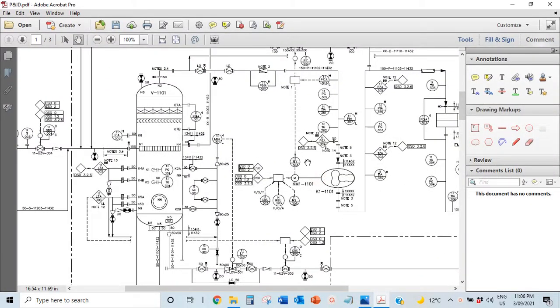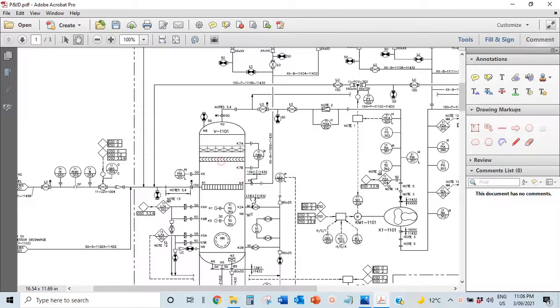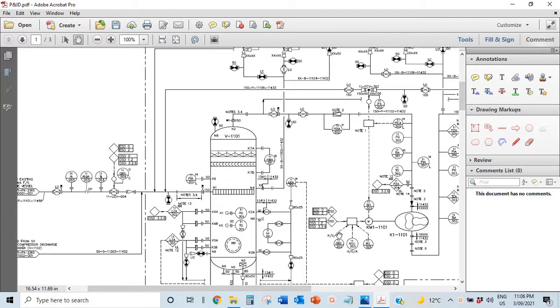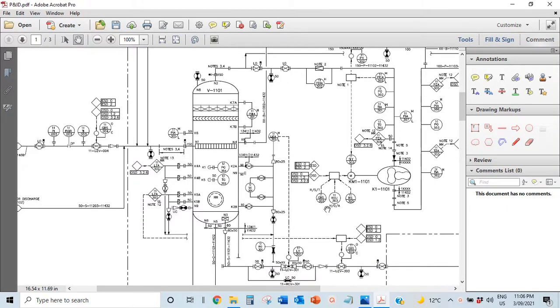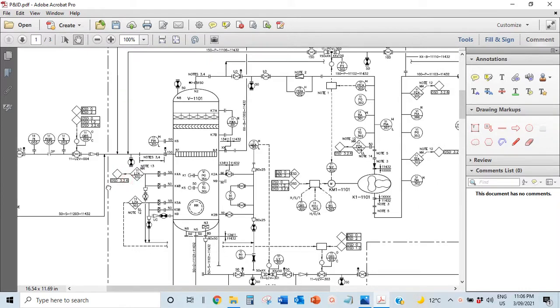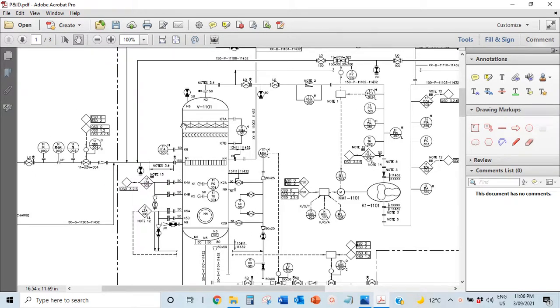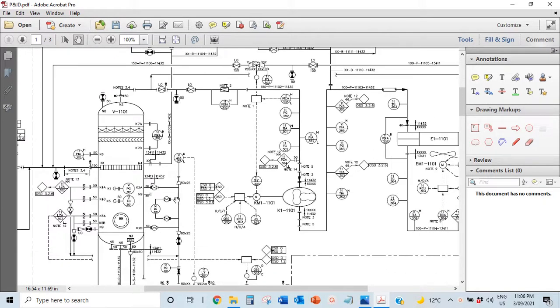This is just looking at 3 P&IDs. For a facility, you may have 20, 50, 100 P&IDs. You could have FERAs, fire and explosion risk assessments, with over 50 isolatable sections, because you have to mark them down in chunks. It's kind of like marking up hazard nodes, but it's a little more technical because we want to look at every piece of equipment and every instrument in that isolatable section.